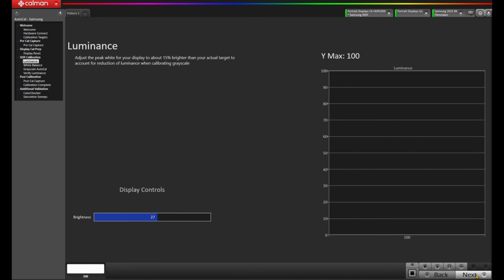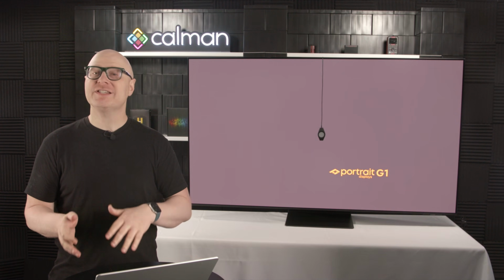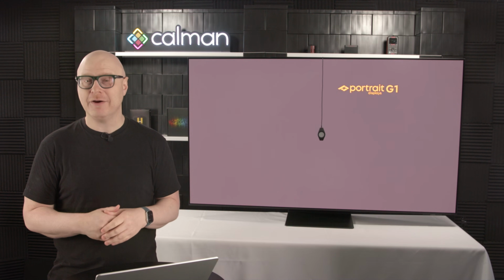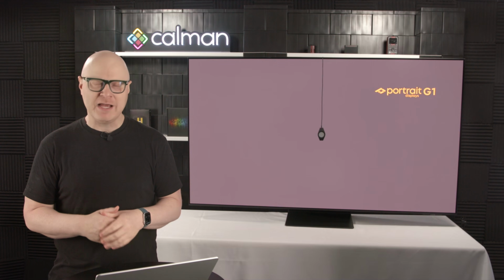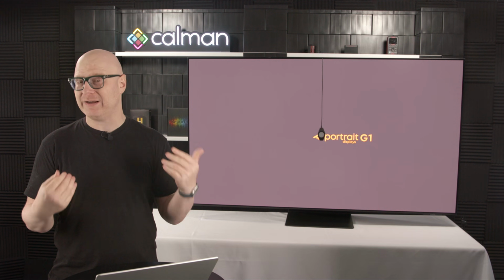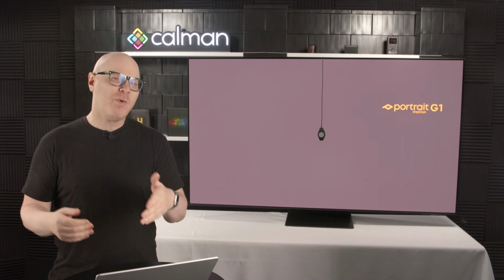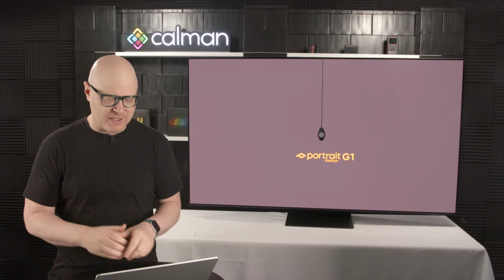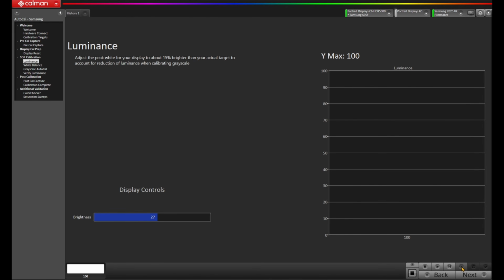We're now at the luminance portion of the workflow. Because we're setting the luminance pre-calibration, we typically recommend setting it about 15% higher than our end target is going to be. That's because as Calman calibrates the display, we're going to lose a little bit of luminance when we correct that white point. So today, why don't we target 100 nits because we are in Calman's studio, so we'll target a reference environment. Let's come down to Calman and press read continuous.